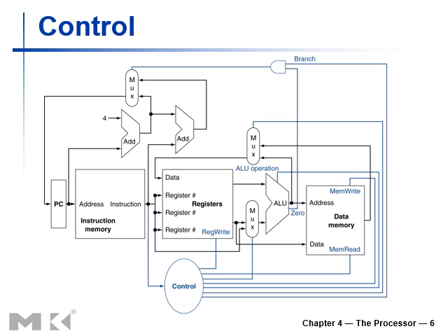Now, how are we going to control that? We've seen the basic components of the single cycle processor, and we've seen that we've got a dedicated controller that basically controls the operation of the processor. So normally we've got a control unit. This is the control unit that controls all the operations depending upon the operation code which you get from the instruction memory. And how the data is processed by this single cycle processor is determined by the control unit.